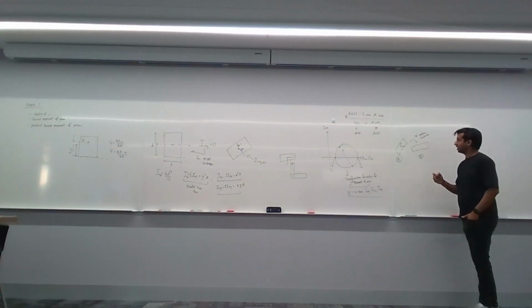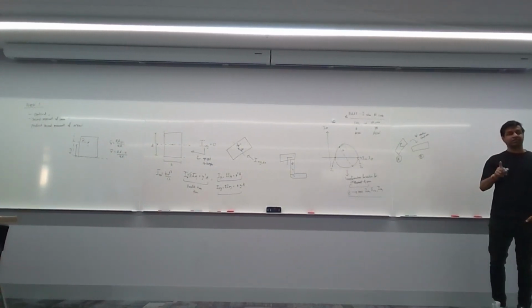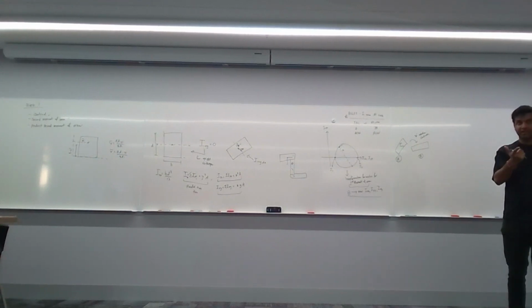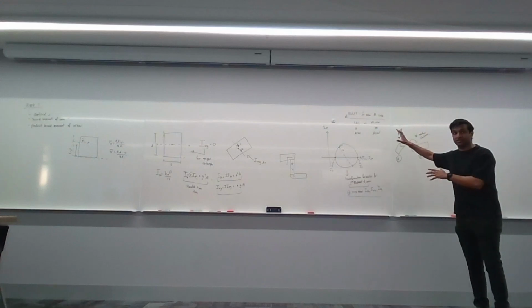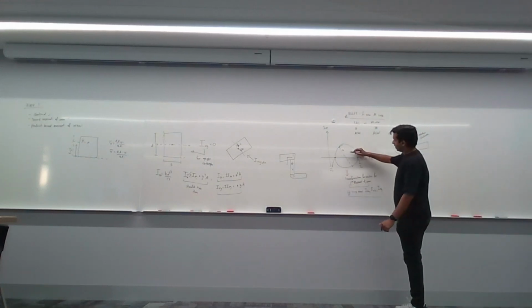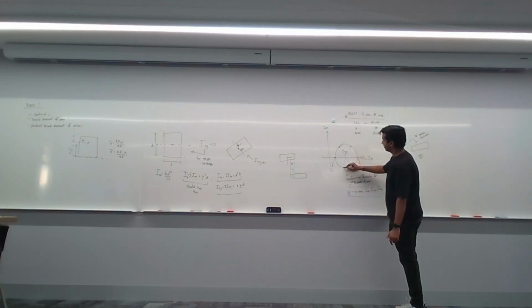Okay? If in real life I rotated 30 degrees clockwise, in the Mohr circle, I'll rotate 60 degrees, but I'll also rotate clockwise. Because this is the I value Mohr circle. It's the Mohr circle for the I values, not for stress and strain. Okay? So that means that there's also a clockwise rotation. It'll look something like this. 60 degrees. And this is scenario B.